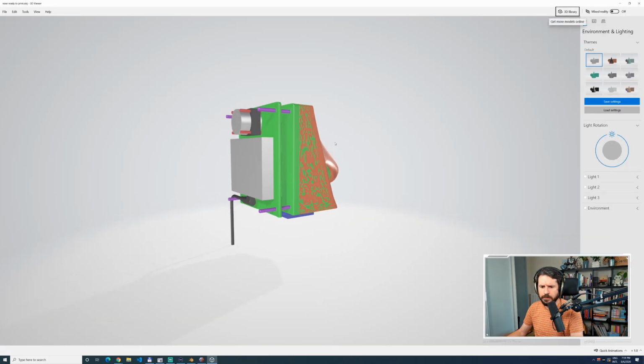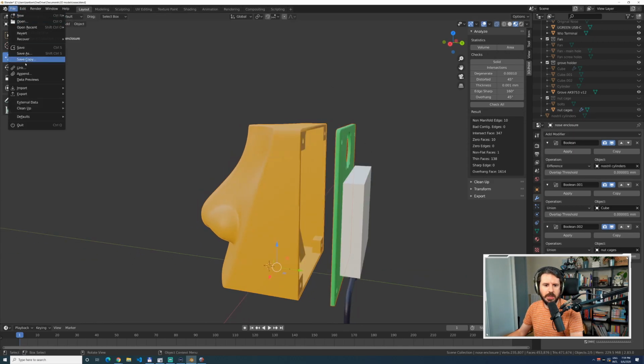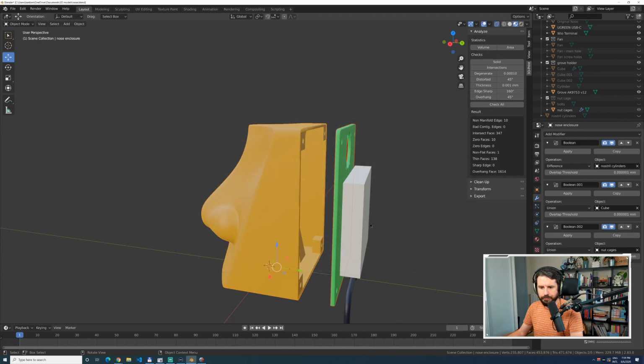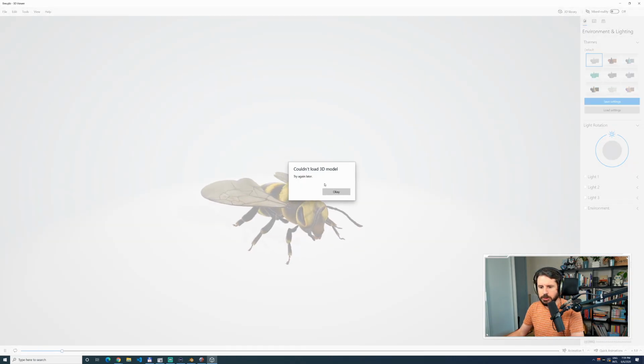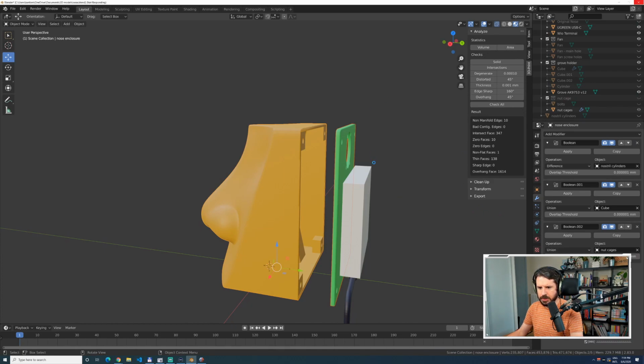Okay. Oh, I exported more than the selection. I forgot to tick the box. So I have only 2 selected, but I only want to export those 2. Export option, selection only, ready to print option. Strictly speaking, I don't need to export the materials, but whatever. Let's wait for the export to finish. Yeah, 9 megs, that's much better. No, that still wasn't finished. Wow, it's confusing. Yeah, Blender is still thinking.